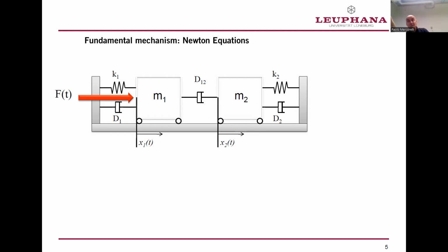Here we have 4 states. Why? Because we have the work of the mass m1 because it's moving. We have not only the work, we have also the potential energy, which you can see in the spring, and also the kinetic energy because it's moving. You have an effort for both. This means 4 states.